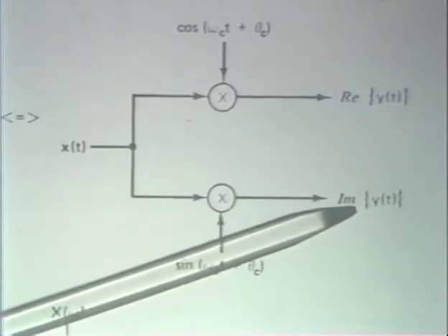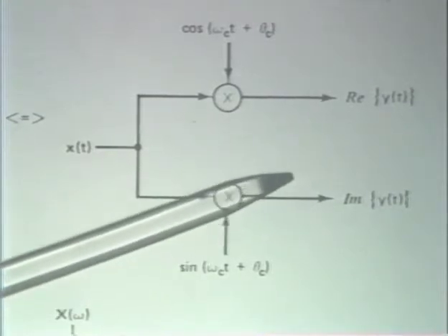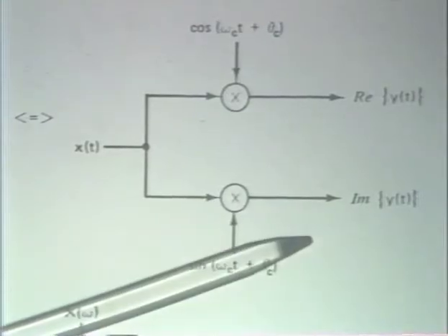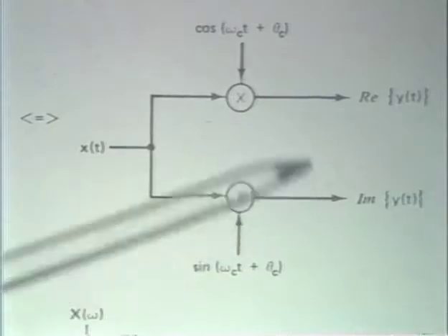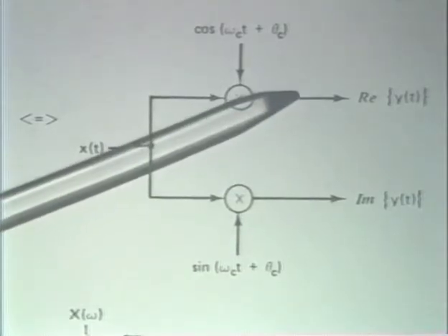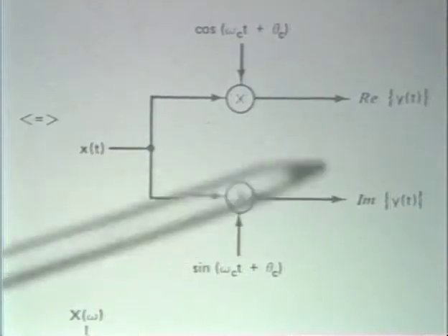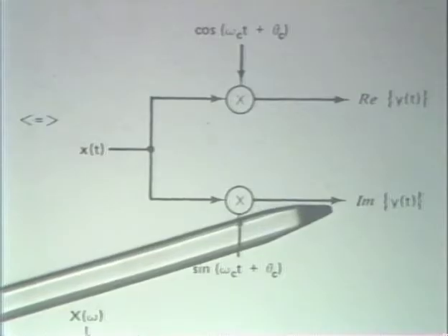And so in effect, this is the complex signal if we just simply think of hanging a tag on here that says square root of -1 or j, and we appropriately combine complex signals following the rules of complex arithmetic. And indeed, that's exactly the way things are done in the real world. A complex signal is simply a set of two real signals.